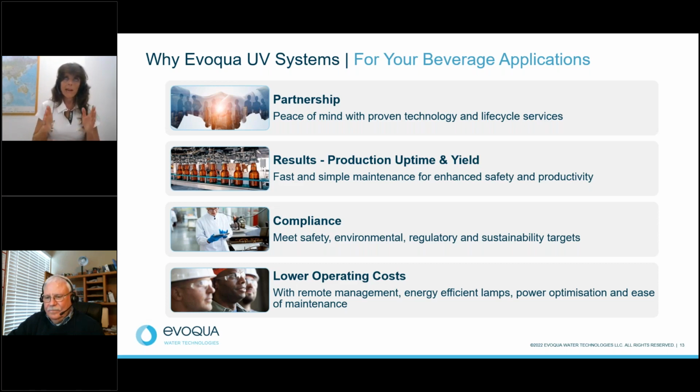As Tony mentioned, if the plant is well disinfected with the CIP, UV at the point of use or on the water recirculation is granting that immediately, by contact with the UV light, the microorganism is inactivated because the DNA is destroyed. So with that, you can be sure that your product is safe, or the water being used in your product or in the process of production of your product is safe.